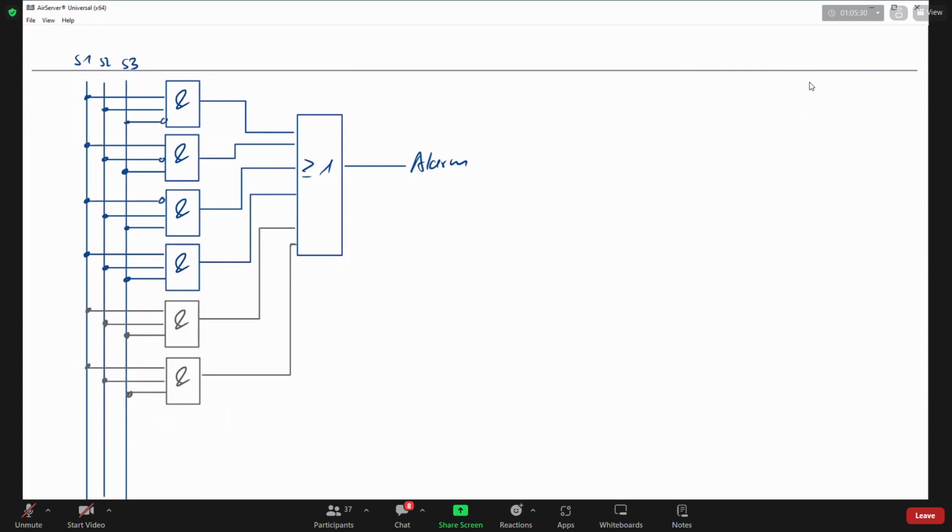So I just added these two gray paths. And if now that path will be true, because S1, S2, and S3 are true, then they will be true as well. But as I have an OR, that doesn't change anything. Clear? Why is this not changing anything if I'm just repeating and adding an existing element which is connected with an OR to that? Because I'm just creating another one at the OR input, but it is already one, therefore it is not changing.